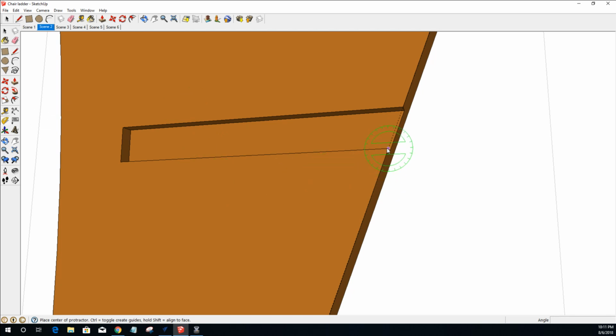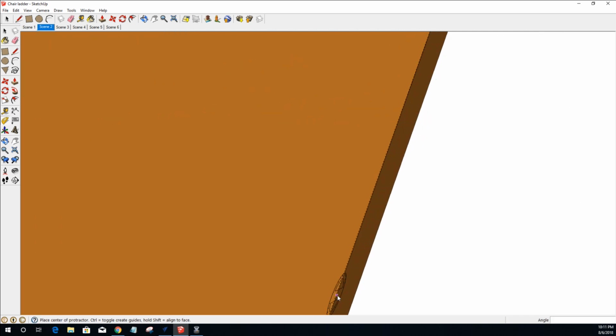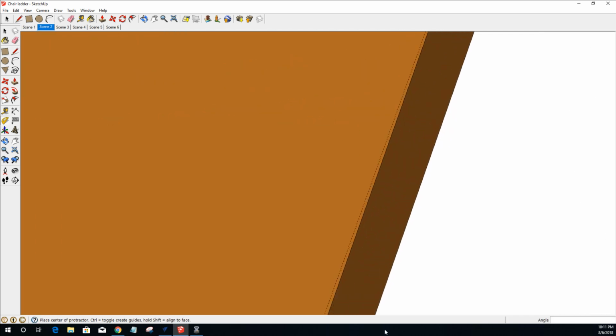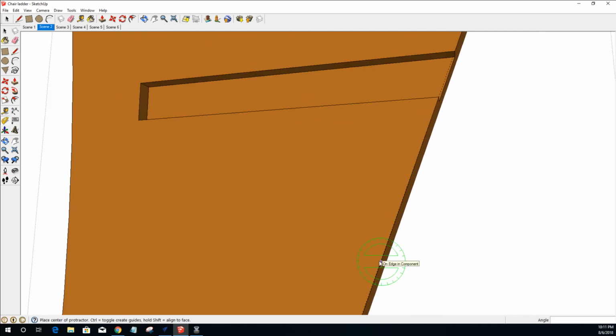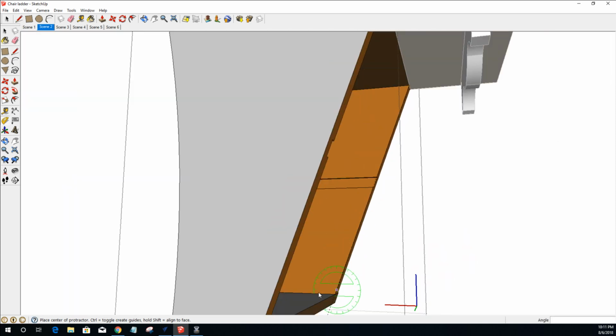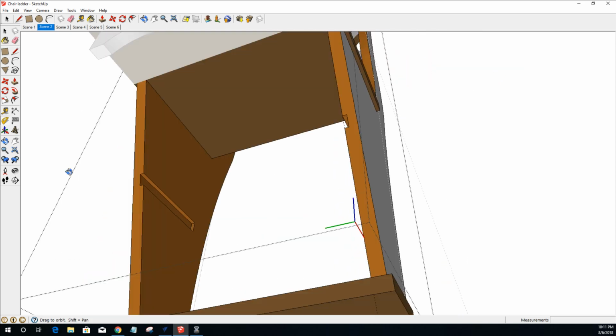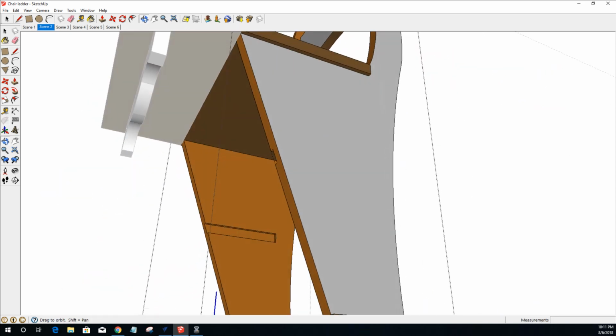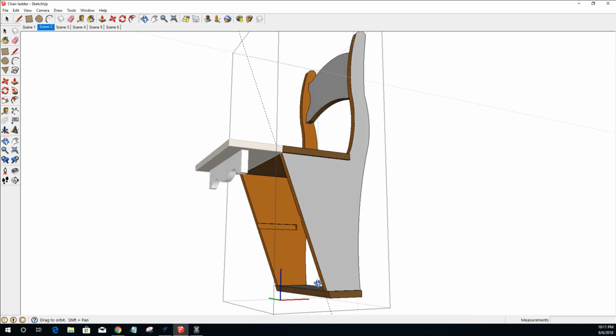But this point, if I came in and snapped to there, 70 degrees, 69.9. It's 70, but I'm not right on my line. I'm off my line, you can see where I'm at. But it's 70 degrees. That angle should make that slot parallel to the bottom of the base, which is what it sits on when it's sitting on the floor. Okay, all right, 70 degrees.